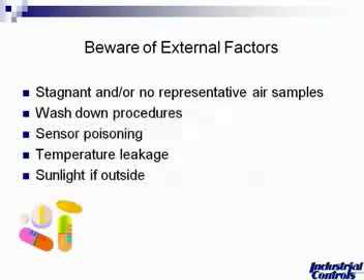Also, during placement of the transmitter, you want to be aware of external factors like windows, where there might be sunlight coming in. That could cause a temperature effect. Opening and closing of doors can also affect readings. You might see spikes in your results. You don't want to place a sensor near any type of blower or HVAC duct. All these things can cause temperature changes, and as we just showed on the previous slides, if the temperature changes, then your relative humidity is going to change.